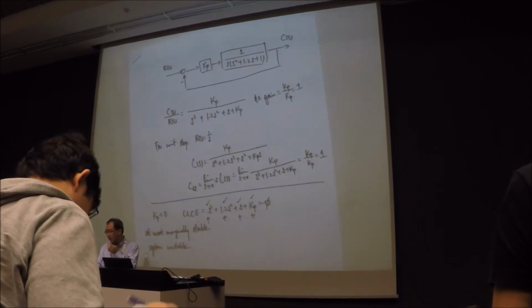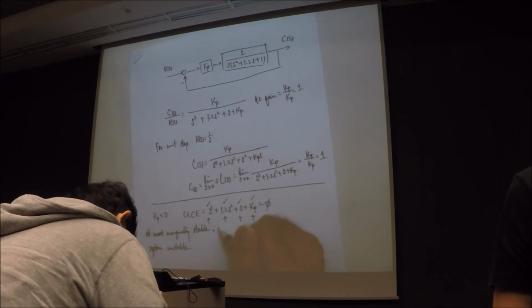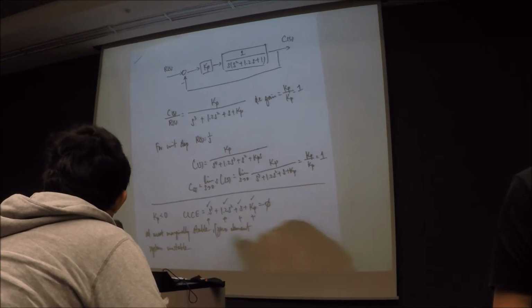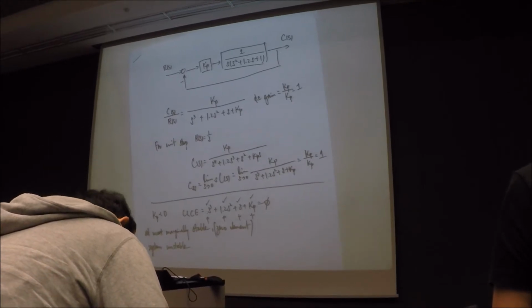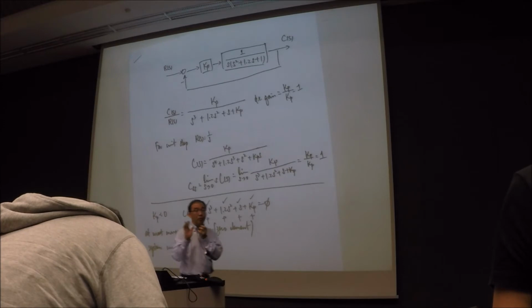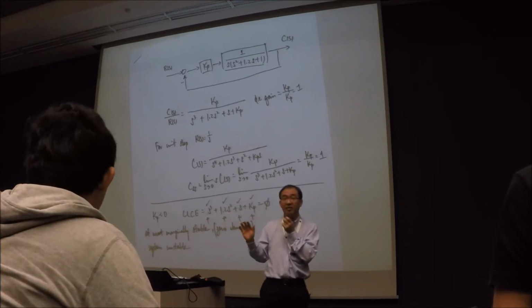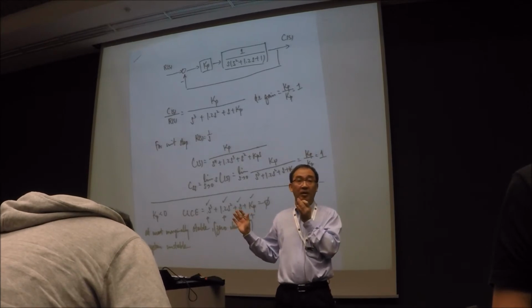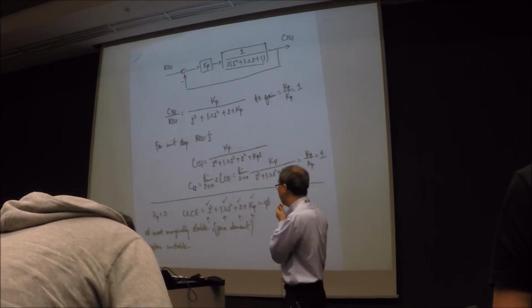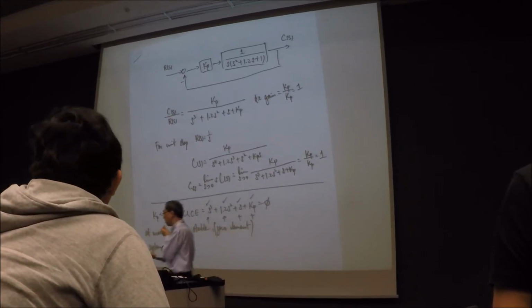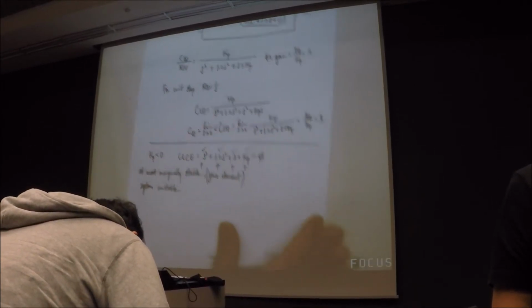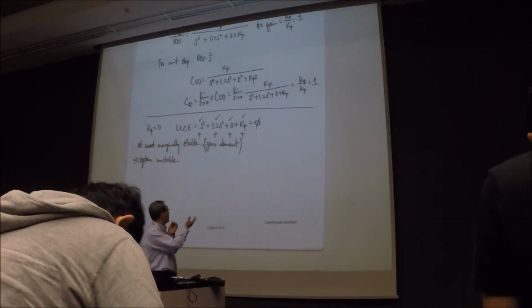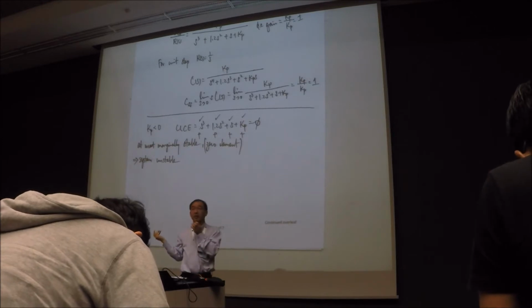When you have a 0 element, we said that it is at most marginally stable. What can we actually conclude when you have a 0 element? At most marginally stable means the system basically cannot be stable. But if Kp has a negative sign, you can straight away say the system is unstable. This is okay to infer, because one of your coefficients has the opposite sign.